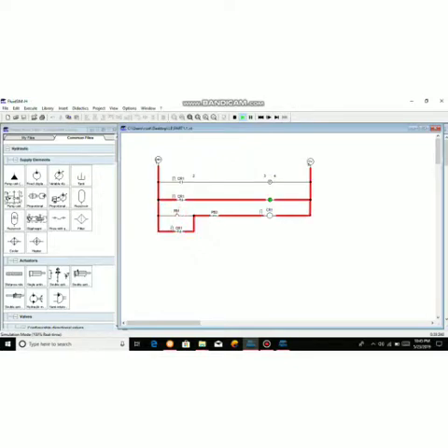At first, the initial state of the circuit is the green indicator lights up as shown in figure 1. If PB1 is pressed, CR1 is energized and affects contact relay 1, and the red indicator will light up as shown in figure 2. PB2 is used to break the circuit. If PB2 is pressed, the circuit will return to the initial state.